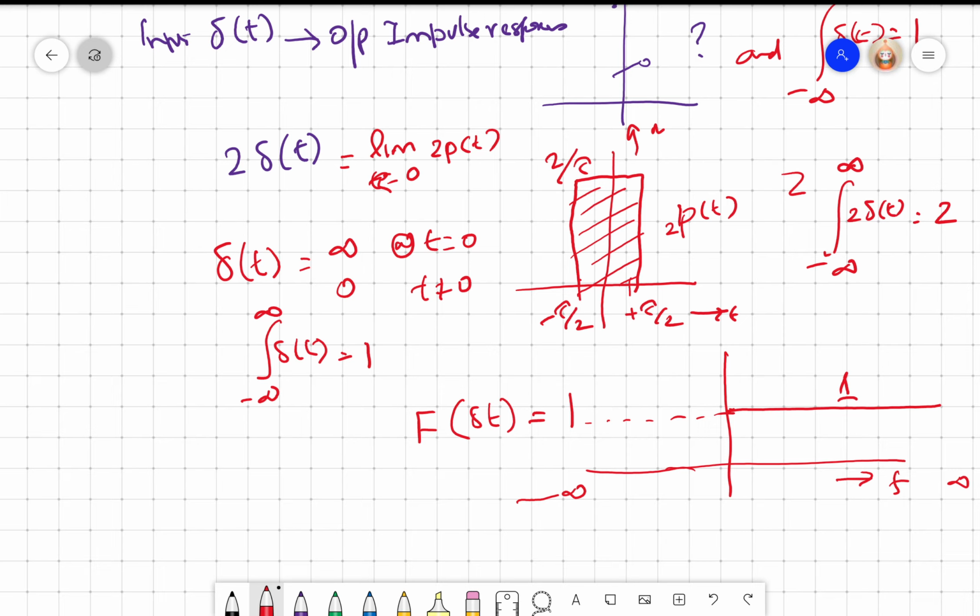So which means instead of frequency response characteristics where I keep varying my sine omega t, the omega of sine omega t from whatever range I want, 0 to 500 radians per second or something like that, when I give an impulse, I actually am varying the frequency from minus infinity to plus infinity and finding out the characteristics of the transducer.